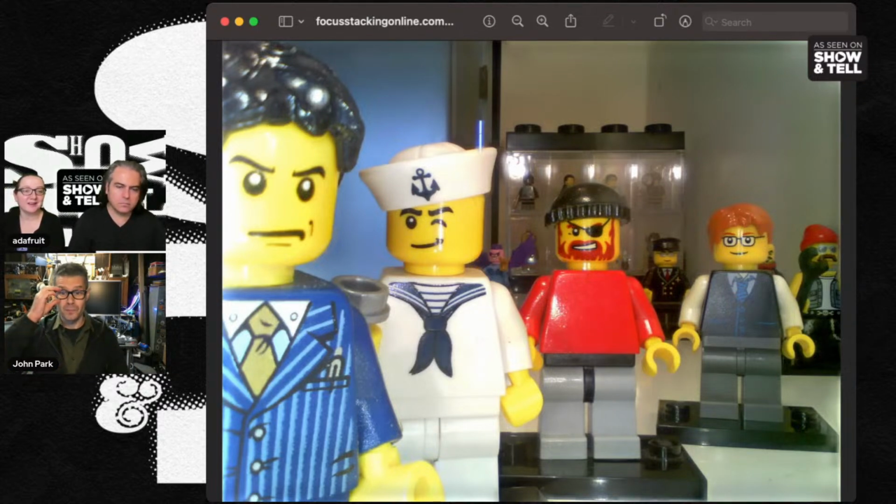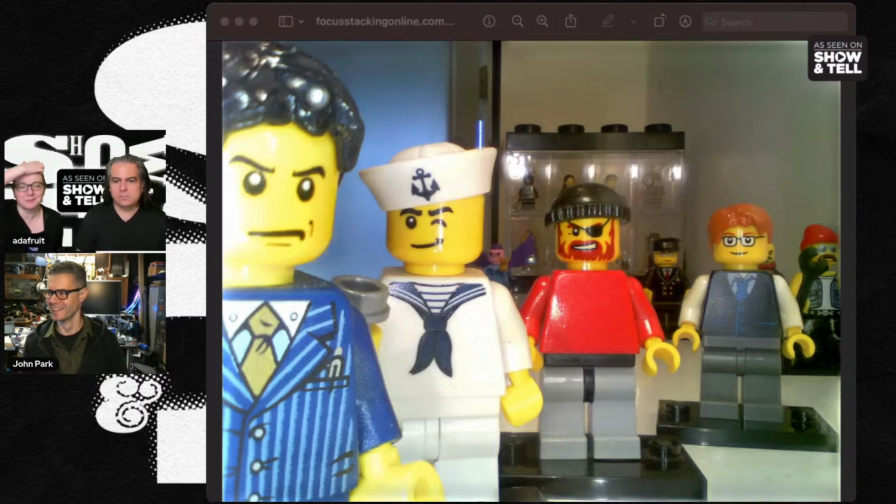And by the way, this was not something I knew that we could do, but we had the autofocus module. And JP and I were chatting, like, there's autofocus, but can we manually focus? And I was like, I don't know, but let me look around. I found a random Linux driver from some other vision project. And they were like, oh, yeah, here's how you can manually set the voice coil current to change the focus manually. And I was like, neat, let's put it in.